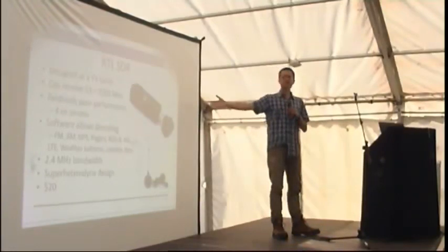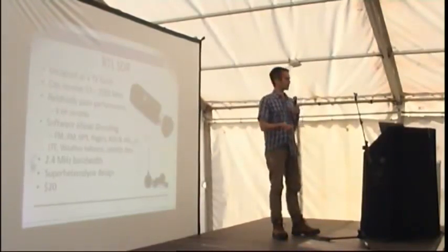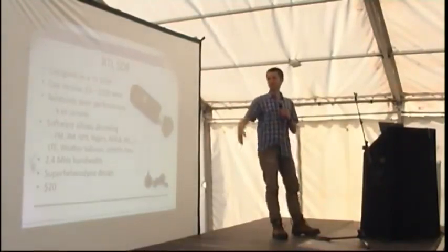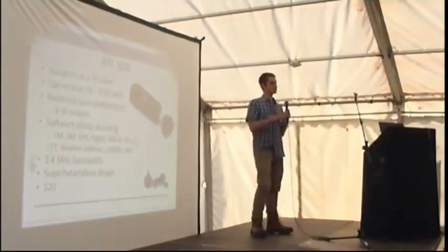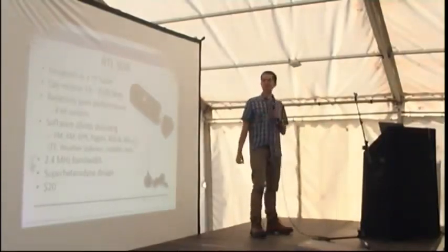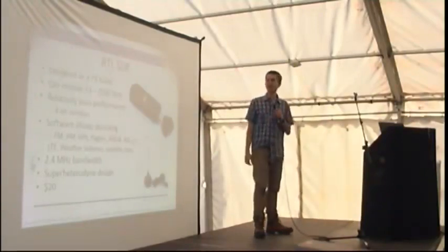And yeah, it's originally a TV tuner. And somebody found out that if you poked the firmware just the right way, it would send you the raw stream. And it receives from about 50 megahertz to 2.2 gigahertz. This varies depending on which exact model you get. Some of them will even go up and hit Wi-Fi at 2.4 gigahertz.